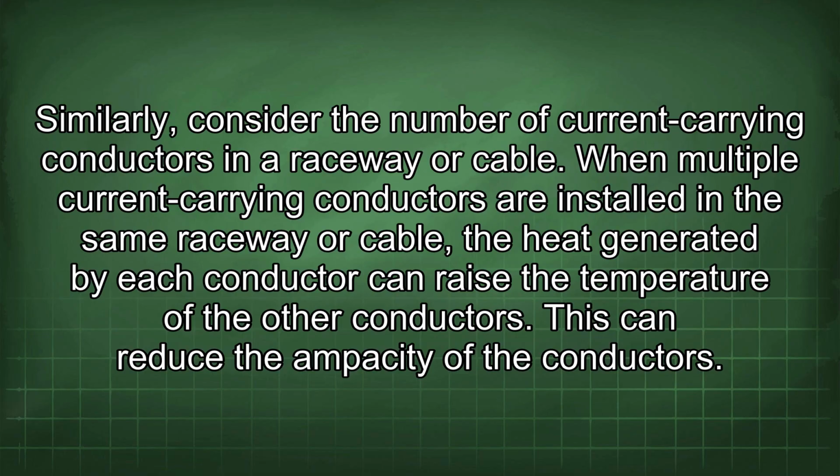Similarly, consider the number of current-carrying conductors in a raceway or cable. When multiple current-carrying conductors are installed in the same raceway or cable, the heat generated by each conductor can raise the temperature of the other conductors. This can reduce the ampacity of the conductors.